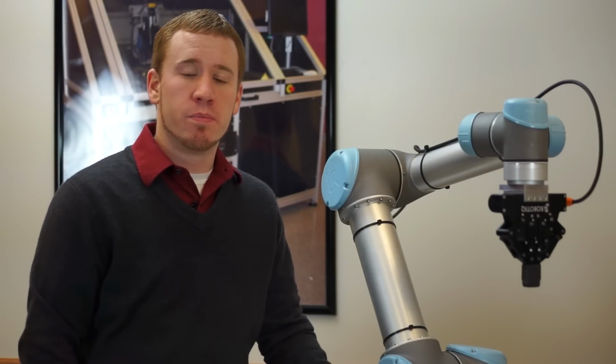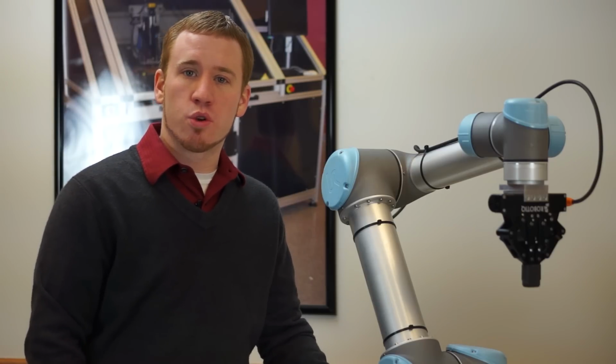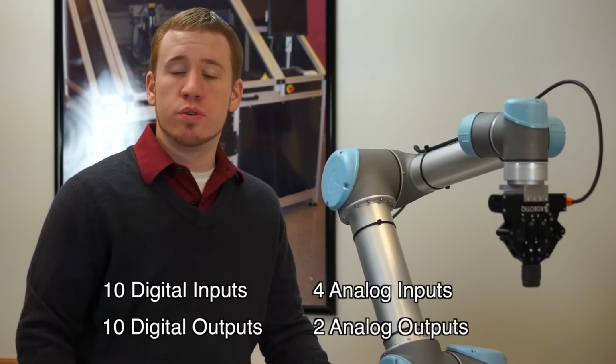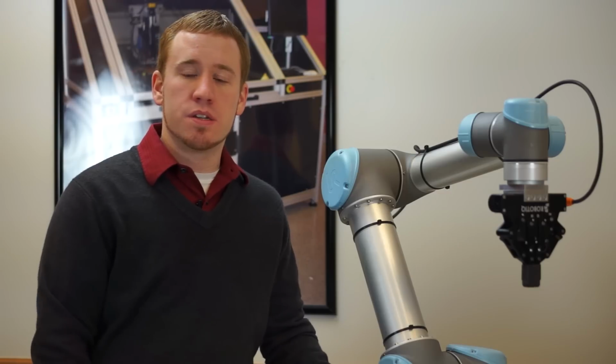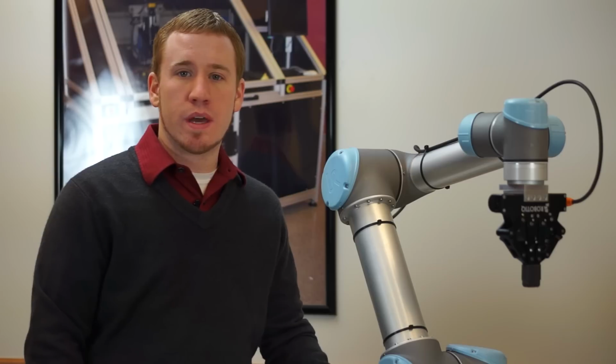We're here to look at Universal Robots and talk about Expansion I/O. If you're familiar with Universal Robots, you'll know that on board the controller we have 10 inputs, 10 outputs, 4 analog inputs and 2 analog outputs. For most applications that's all that you're going to ever need. But in a lot of advanced applications where you've got multiple machines or a bunch of different devices, you're going to need some Expansion I/O.